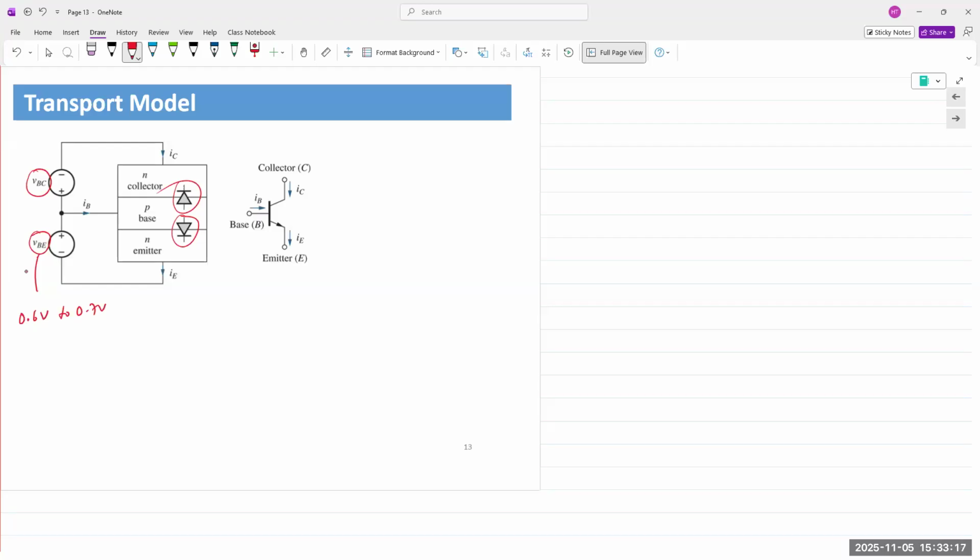One difference between the FET and the BJT is that for an FET, the gate current is equal to 0. In a BJT, the base, which is the controlling terminal, will require a certain amount of current for it to actually operate or turn on. For MOSFETs, it's again the same thing.